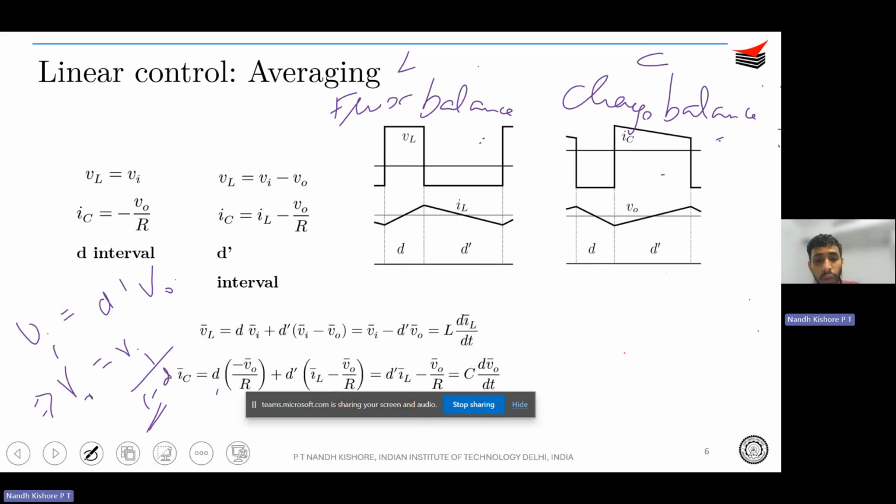That is, the capacitor's voltage will not exceed. So VC is fixed. Similarly, IL is fixed. It's a capital IL which is fixed, and a capital VC which is fixed. So obviously, understand, right? V is equal to L di/dt. Correct. So if the net value of V is zero, then it means that di/dt is zero, right? There is no net increase in inductor current.